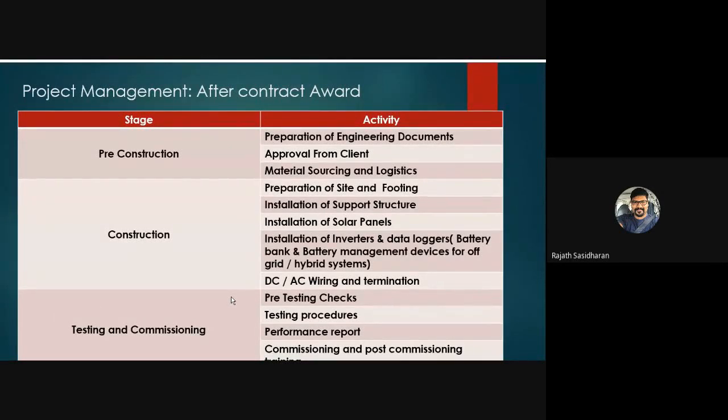Structural drawings play a very important part, because in case of a roof, if you're planning to put such heavy equipment on top of a roof, then the architect or the civil engineer who designed that building needs to verify that yes, you can have that kind of a load. And structural calculations are also used to see what the wind effect is on a solar photovoltaic system. Even if it is flat or even if it is tilted, you need to calculate what is the wind stress acting on the solar photovoltaic system. And these are the structural details.